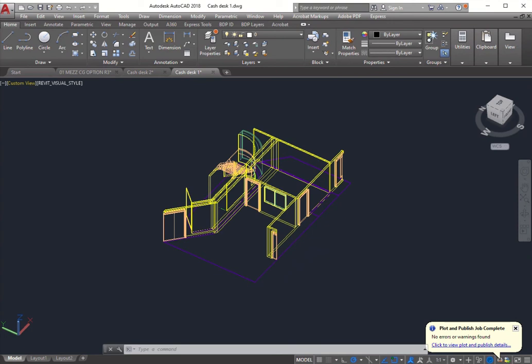Today I will be going through some basics of AutoCAD printing in this short clip. To begin with, the difference between model space and the layout space in AutoCAD is that you draw in the model space, usually at 1:1 scale, and you print from the layout space, where you can change the scale or even have a couple of different scales from various viewports. But first, let me explain the viewports.